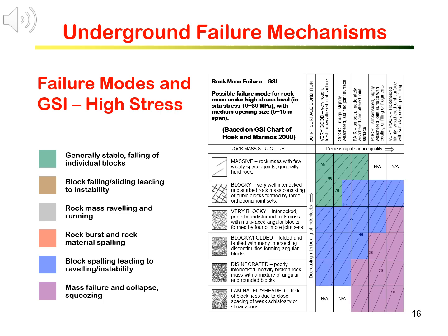When stress becomes high, we are going to face squeezing in poor and weak rock mass, shown in purple, while high stress may help to stabilize the excavation for good and solid rock mass.